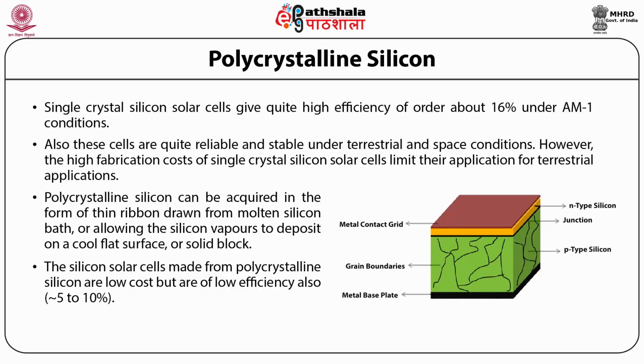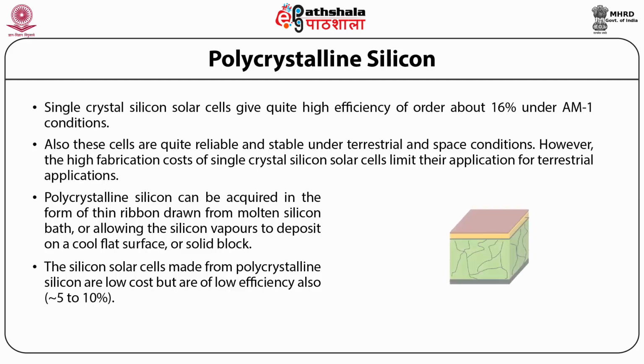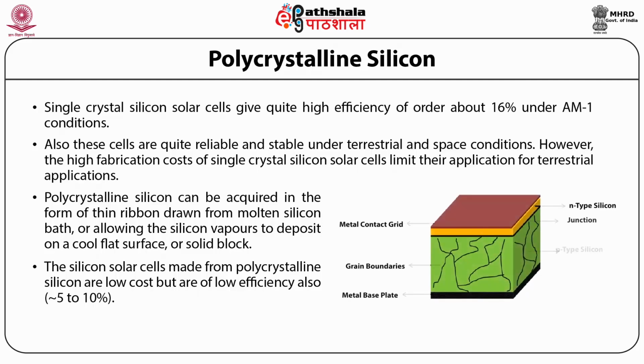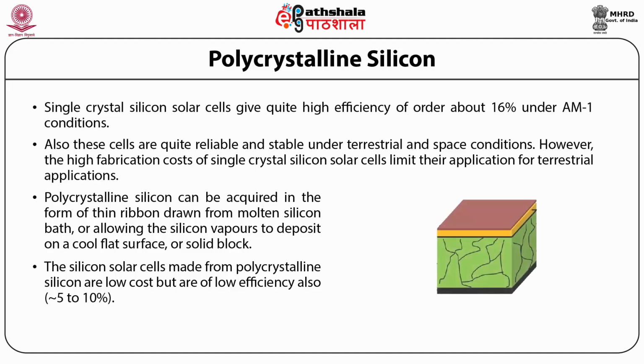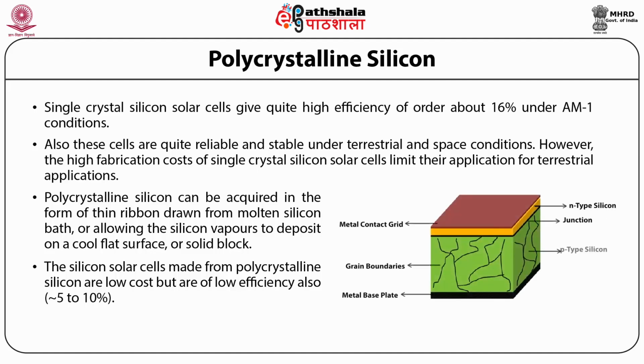The idea of a metal semiconductor junction is quite attractive since it simplifies the manufacturing process and is of low cost. These cells show a similar short circuit current ISC and low open circuit voltage VOC as compared to p-n junction cells, resulting in low cell efficiency.